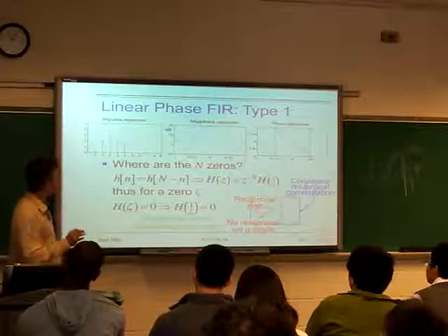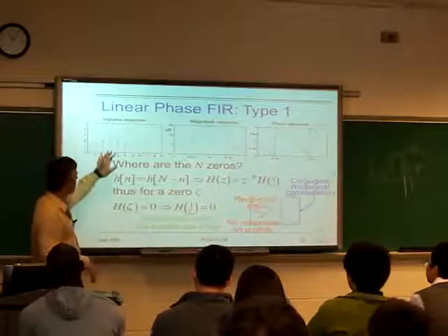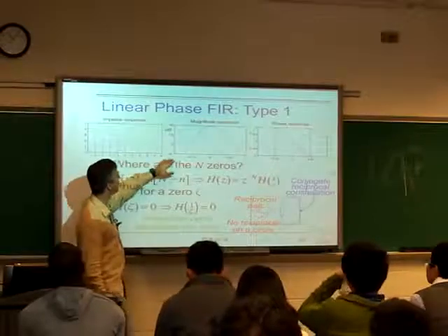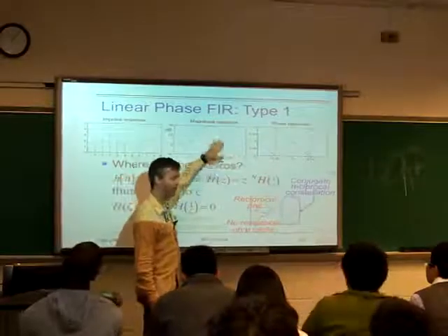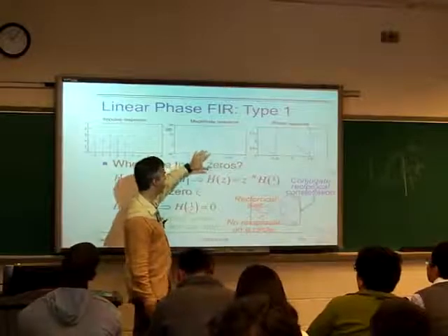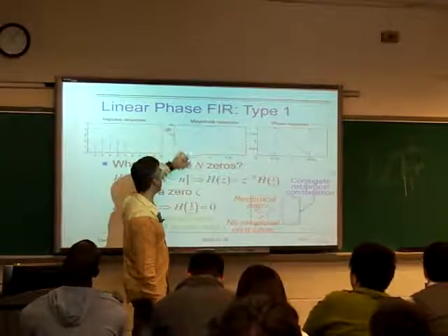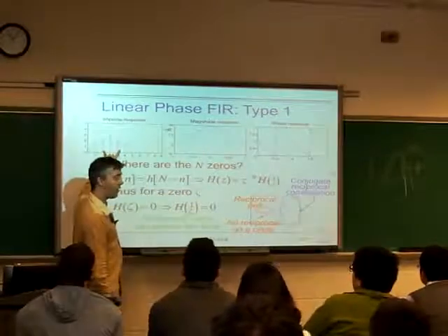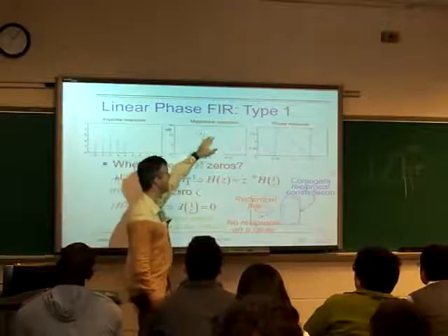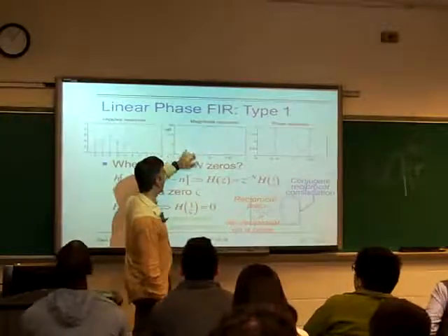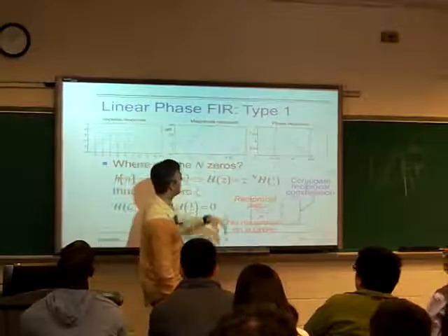So now we have this symmetric impulse response whose Fourier transform we know is going to be some kind of real part made out of cosines. Here I've plotted it in dB scale. So even though this is only a fourth order filter, we've only got cosine omega and cosine 2 omega in here. It looks a little bit sharper than that just because of the log nonlinearity.